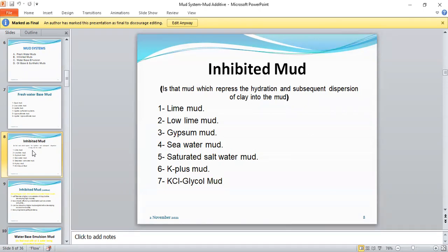It will withstand the cold area. It will prevent the mud from freezing, from becoming blocked, from forming hydrates because of the heat effect of glycol. Glycol can also give you lubricity in your mud. So these are a list of inhibited mud systems.